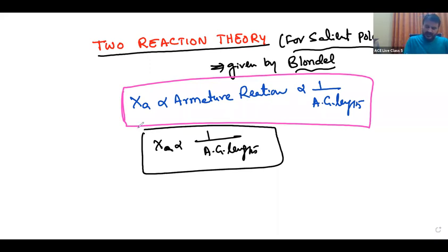Now, first of all, let us see one by one for the cylindrical machine and the salient pole synchronous machine. In a cylindrical rotor synchronous machine, only a single reactance is sufficient, because the air gap is the same everywhere. Whatever the power factor may be, it finds the same air gap. So one reactance is sufficient.